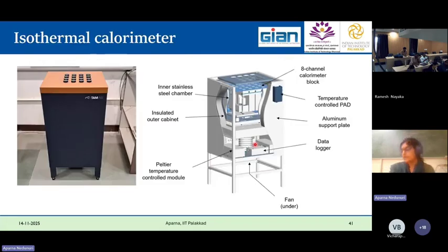If you look at isothermal calorimeters, there are different vendors which provide them. You have TAM Air, and you have several other vendors. Here I am showing a picture of a TAM Air isothermal calorimeter from IIT Bombay, where I did my PhD. If we dissect this, we can see how many caps? Four caps in one column, and you have four such columns. You have 16 caps over here. 16 caps would refer to 8 channels.